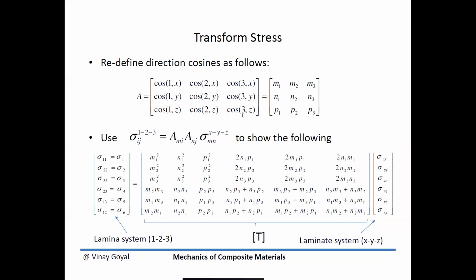1. What you will find is that these two terms will be 0, these two terms will be 0, and this will be 1. And then these four terms here will be either cosine alpha or sine alpha, where alpha represents the fiber angle. But regardless, in the most general formulation, we can call this M1, M2, M3 for the purposes of simplifying what we plan to do next.